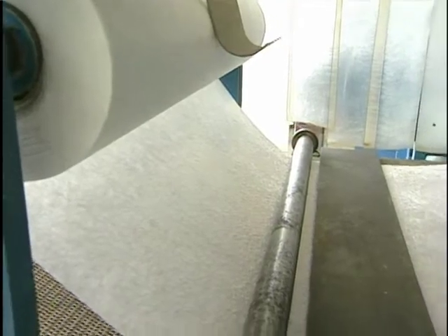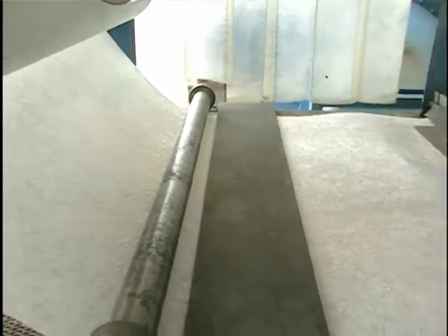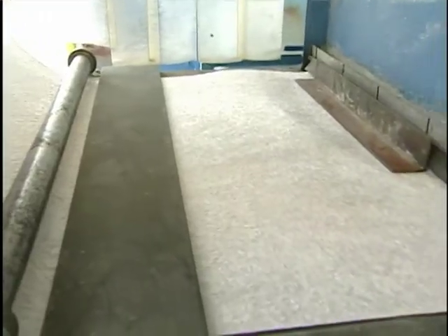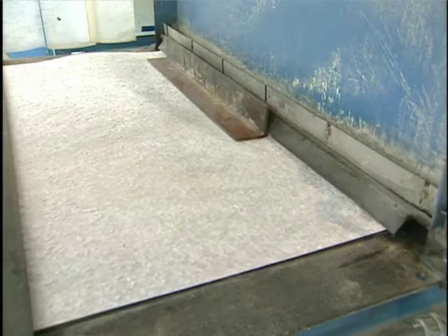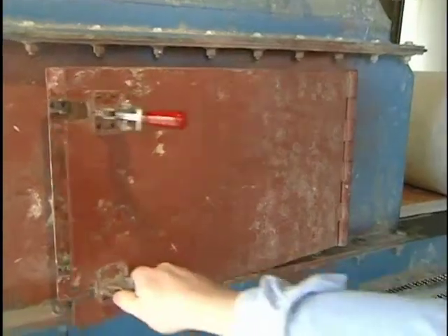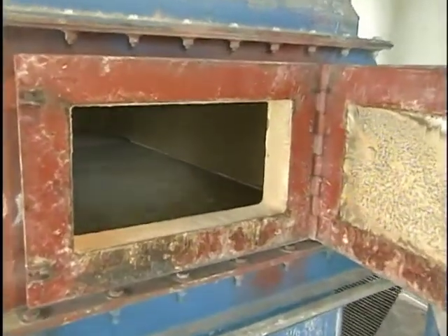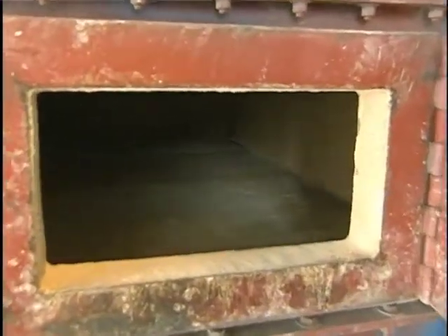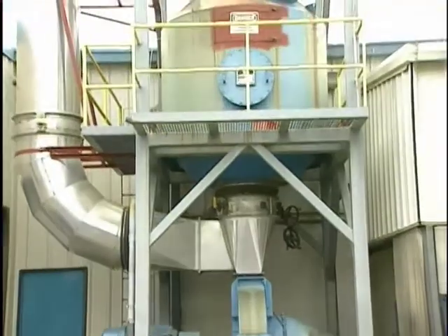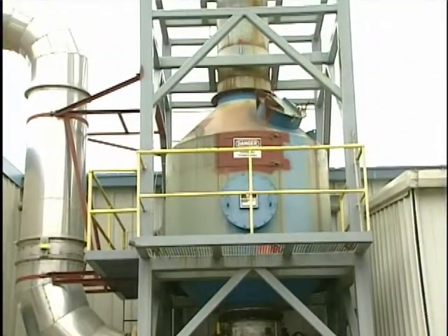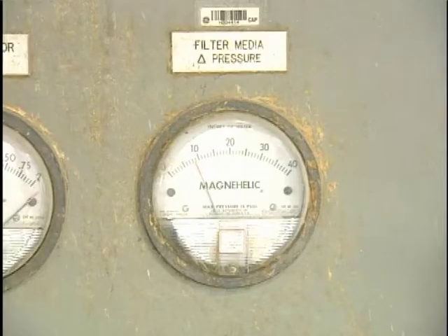HVAFs collect particulate matter by impacting the particles on a linear filter mat that is slowly unrolled and banded around a porous rotating drum, or travels over a flat bed. The contaminated gas stream passes through the rotating drum or flatbed, leaving the particle cake on the outside surface of the mat. These units may have a mist eliminator on the outlet gas stream to capture droplets escaping the filter mat. As the pressure drop across the filter increases, the mat is advanced to expose fresh media to the gas stream.